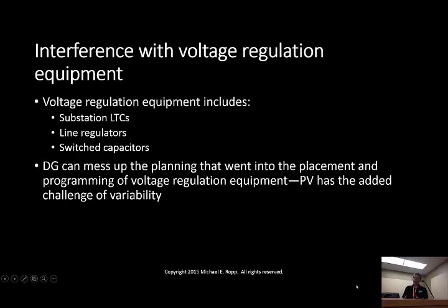As you're aware, when I've got more than one regulator on a feeder, effectively they're coordinated, not all that differently than protection is. We want to make sure that if a voltage regulator downstream is switching, one upstream isn't going to change in response, and vice versa. So there's planning that goes into making sure that the amount of chattering between these things is minimized.